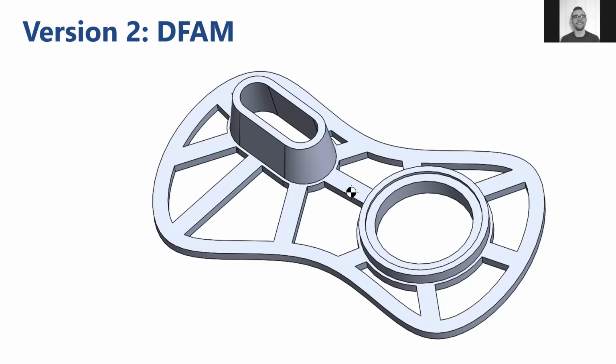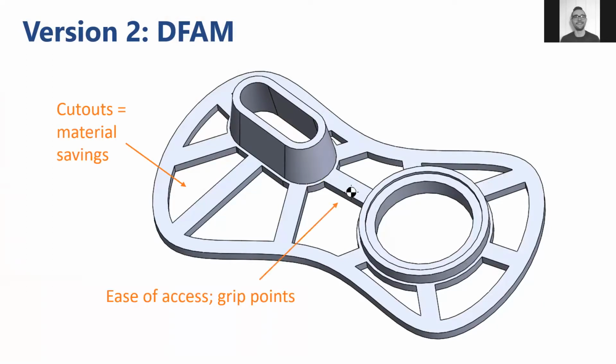So at this point, a lot of people would just jump off, print it solid, and call it a day. But we want to see what's really going to go on with this part. So when we're doing that, before we're even printing, we can look at where this part may have some stress and may need some more reinforcement. And so we can see we've highlighted all of the features here: cut-off roof handle, the cutouts, ease of access,